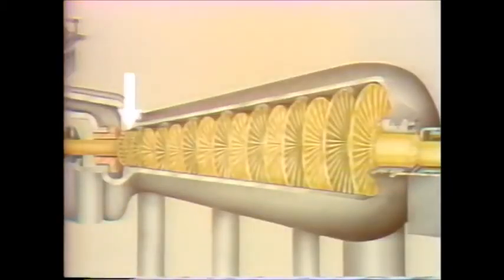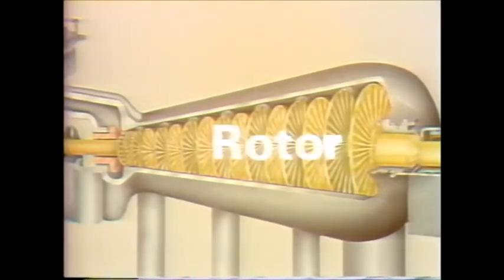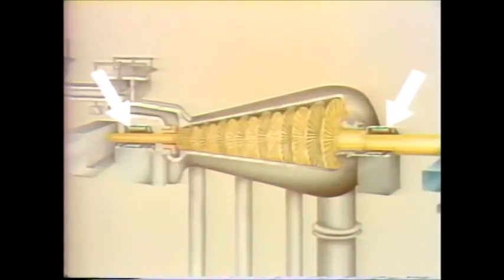Now notice that the moving wheels increase in size. This is necessary to get as much work as possible out of the steam and to accommodate the expanding steam as it flows through the turbine. The shaft, the wheels, and the blades are collectively called the rotor. The rotor is supported at each end by bearings and is housed in a casing called the turbine cylinder. Mounted to the turbine cylinder are diaphragms. The cylinder and diaphragms make up the stationary parts of the turbine unit.